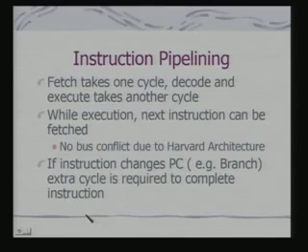Okay, you can ask your question. For more efficiency, why did we only go for 4? We have gone for 4. This is an example of an architecture by 4. This is how the demand of the internal design was, because this processor, I said, is for low end applications. So, it is not required to support extensive multi-stage pipelining. When you go to a complex processor, you will find more complex multi-stage pipeline support. Here it is just a support such that I have an overlap of instruction execution and instruction fetch.